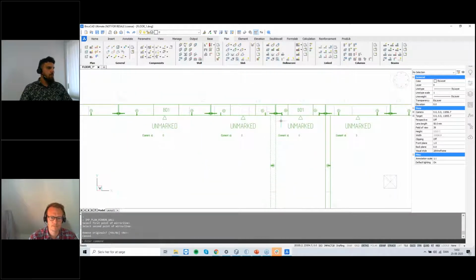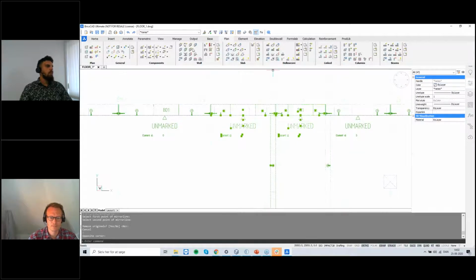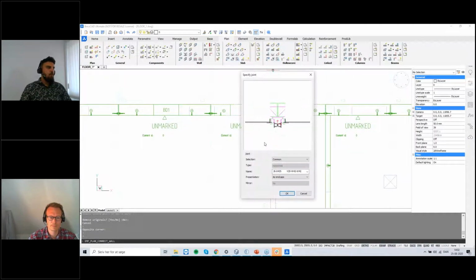One thing I didn't show you, of course, is that there is a possibility to connect sandwich with solid walls according to your specifications. I have this joint here. Again, wire loops, a solid wall, a 200 millimeters wall, come here, or the two 420s, press OK.